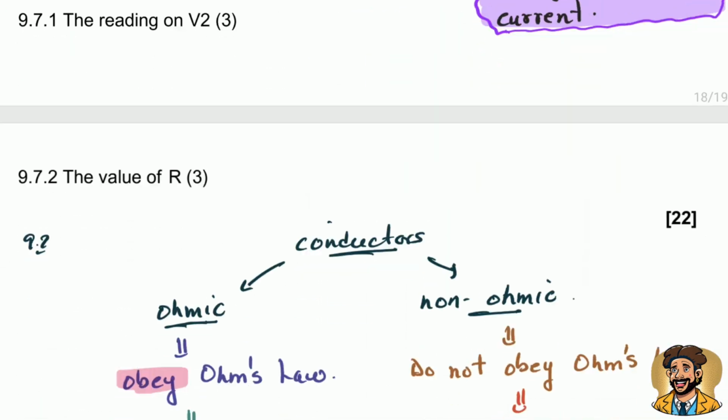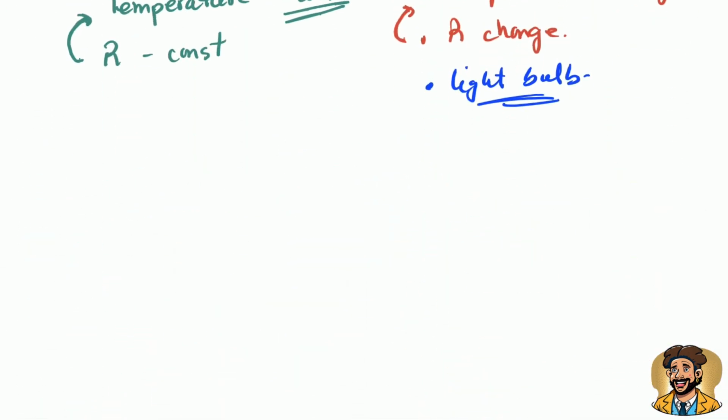If you remember from grade 10, you know that the potential difference in series is the addition of the potential differences. So if we take that resistor as a unit, we can say that the potential difference total, which in this case is the EMF, is going to be equal to the addition of the potential difference of all the resistors. So that will be the potential difference of resistor 1 plus the potential difference of the lamp, plus the potential difference that goes through the whole parallel connection.